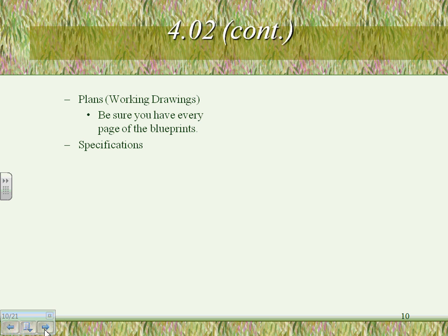Don't put it underground. Don't put anything underground less than one inch. It's not worth digging a trench and putting in a 3/4 inch PVC conduit, less than an inch. So where do you find this information? Specification.